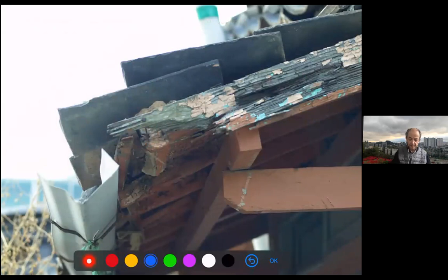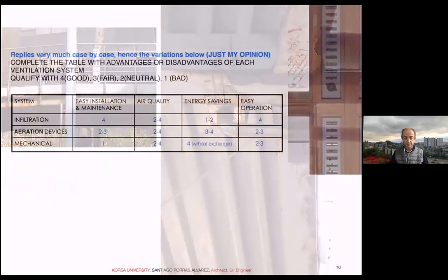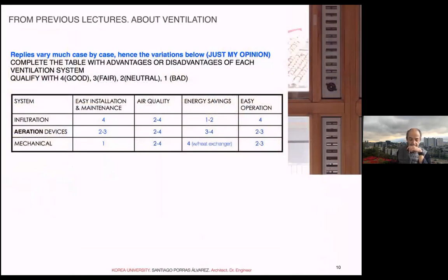So when you have a roof, if we make this section, if you have the timber, you need to have, of course, the tiles, right? You need to have a final tile and some protection in this area, so the water will drip and will not be happening as it happens here. And we saw already, we have examples of not using drippers in our campus.